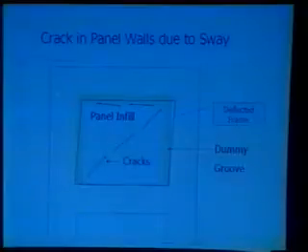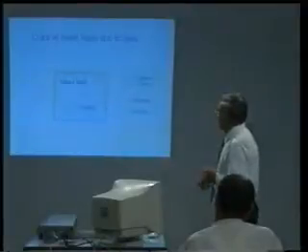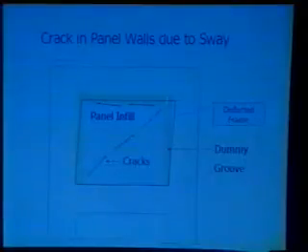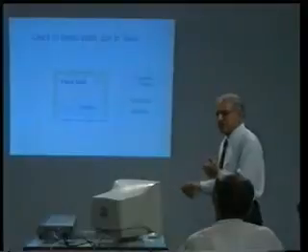A portal frame is going to sway under load, whether it is wind or earthquake condition. This is going to create shear stress and an extra amount of force from both sides. The drag forces are going to crack it up like this. This can very easily be avoided by providing a dummy groove all around and filling that groove with a compressible material like an acrylic filler or any other filler which is convenient at that location.